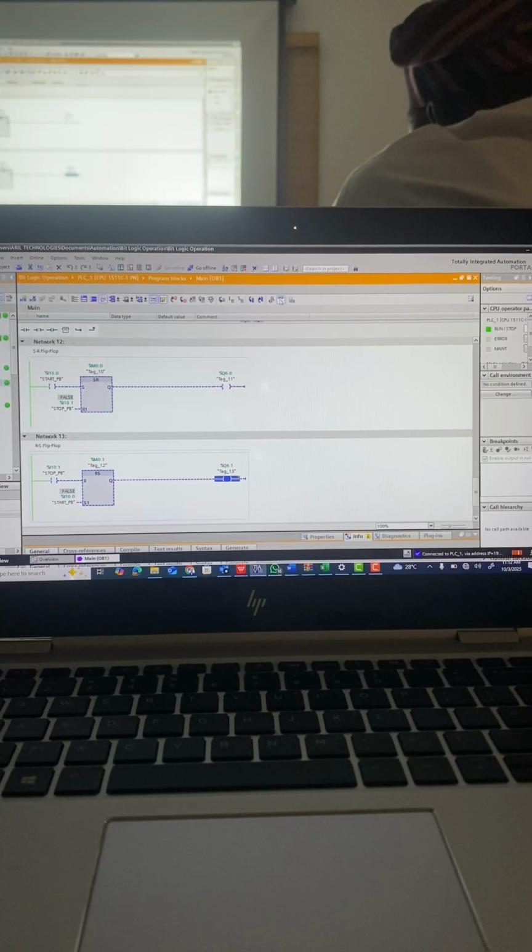Now, based on that analogy, what can you say about them? So I think it can find application in safety conditions. Thank you. Let's say maybe the machine is currently working and you need to immediately stop it, regardless of whether it is being started or not. So you can use an SR flip-flop in that case, where you immediately press the one that has a reset to stop.